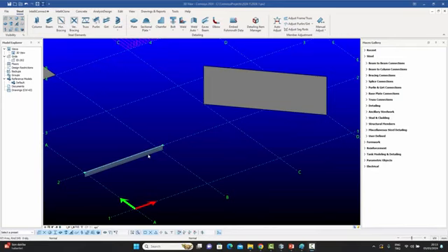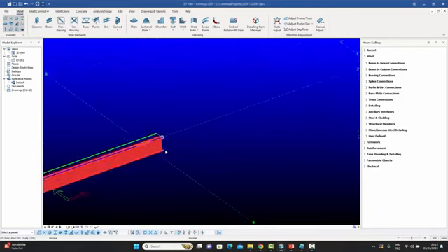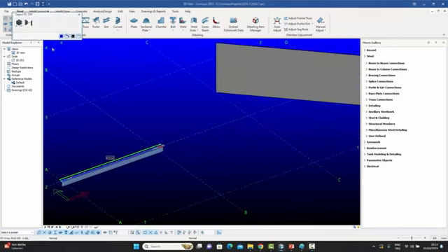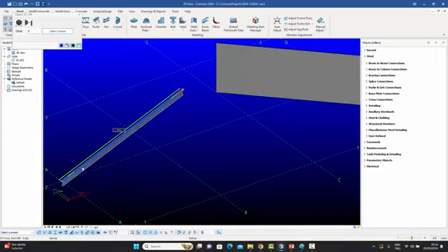Or, for instance, I could once again select the handle over there. And instead of giving it a normal move in which I have to enter coordinates or distances, I can just say move the definition point to a surface, press this button, and I can even give it an offset. Let's keep it 0 at the moment, but it's asking me to select a surface. And when I do that, I can just select a surface on the screen. Then this one is taken perpendicular to that point. This is basically a perpendicular extension of that point to the surface.